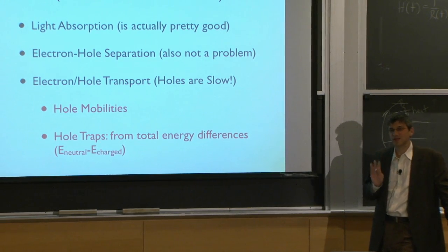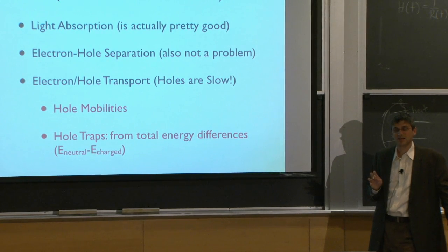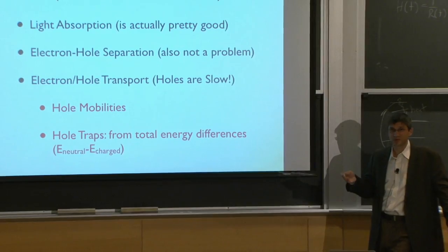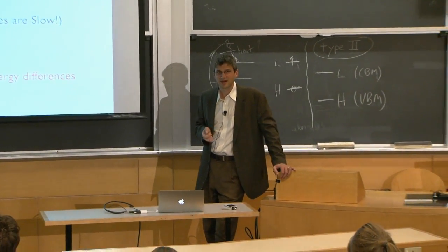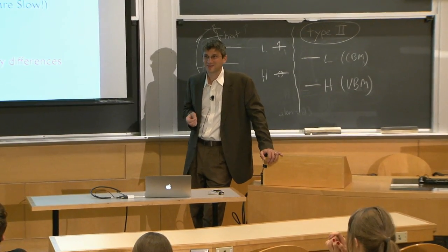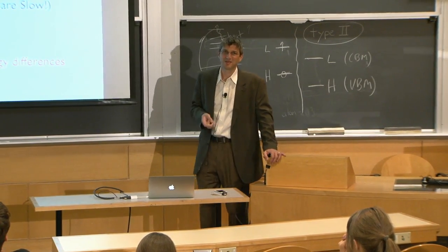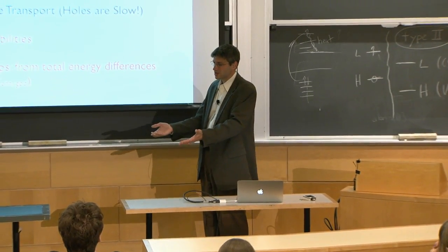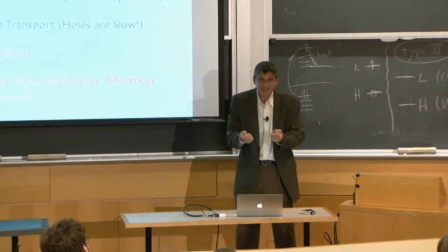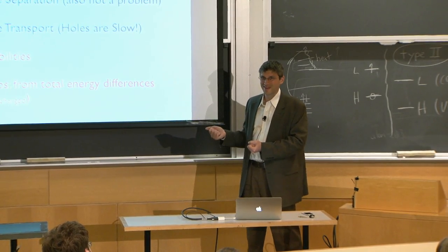So you get an immediate 30% hit on your performance when you have an amorphous silicon solar cell. And that is a 40-year problem, 30-year problem that is unsolved, right? I love problems like that. Why? You hold it out under the sun, and because of the sunlight exposure, the mess is getting messy in a bad way.